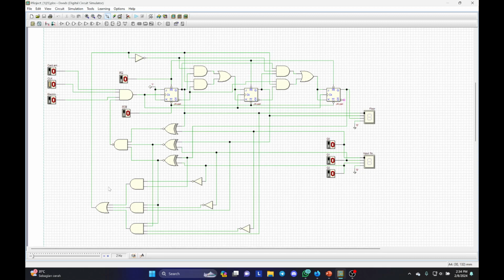And the one on the bottom is section C, which is going to compare if section A is greater than section B or section B is greater than section A. If section A, which is the current floor of the lift, is greater than section B, the floor that we inputted or the button pressed inside the lift, then this comparator will output 1, indicating that it's going to ask the lift to go down.